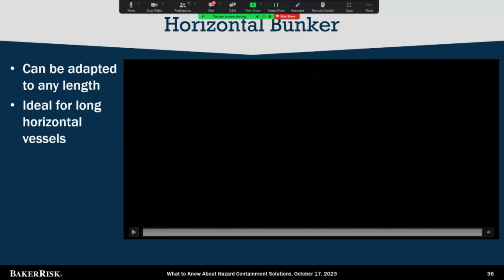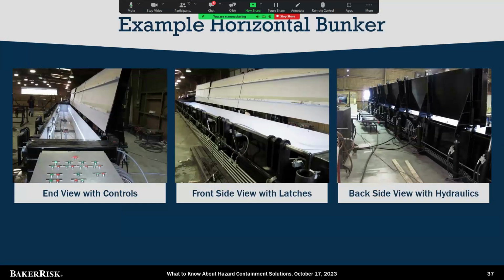They might test a long tubular that has a bull plug or an end cap. And if those get accidentally thrown, well, they're fairly significant, so that substantial end wall is designed to withstand that type of an impact. Here's some photos of an example that's been built.